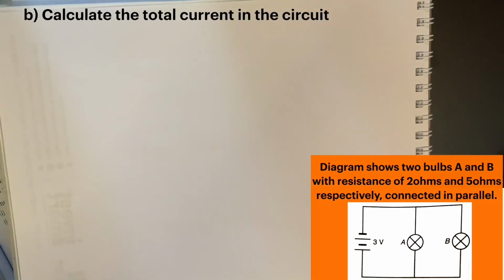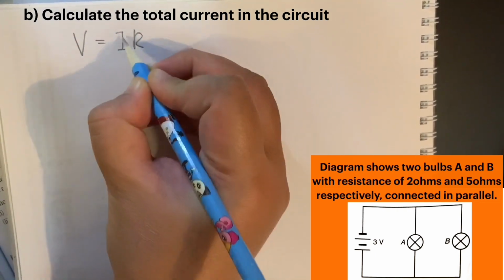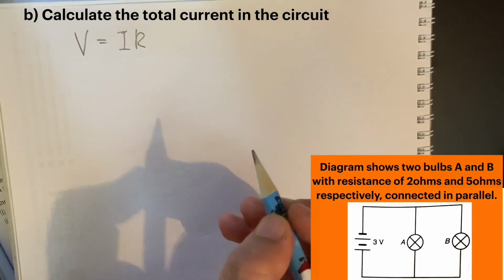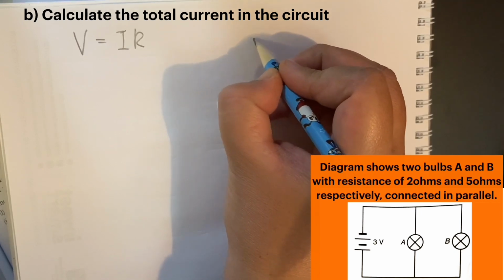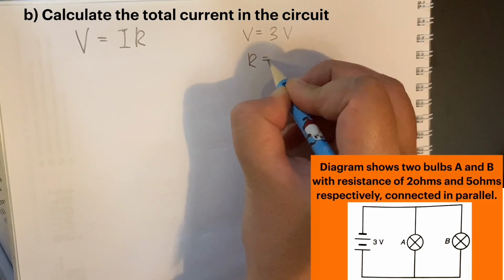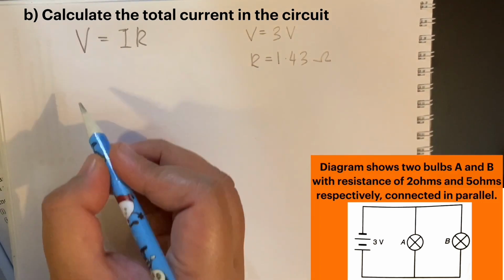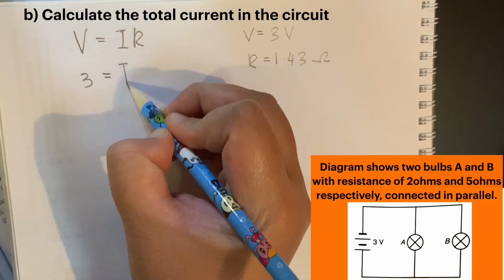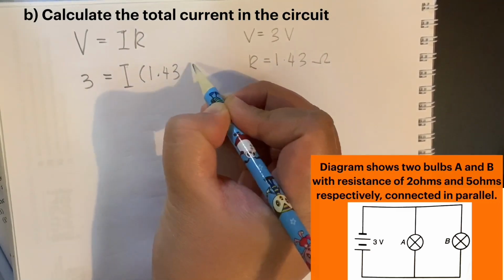To find the total current in the circuit, we use the Ohm's law. V equals IR. V for the voltage, I for current, R for the effective resistance. So we know the voltage in the circuit as 3 volt and the effective resistance as 1.43 ohms. We substitute the value: 3 equals I, which is unknown, times R, which is 1.43 ohms.